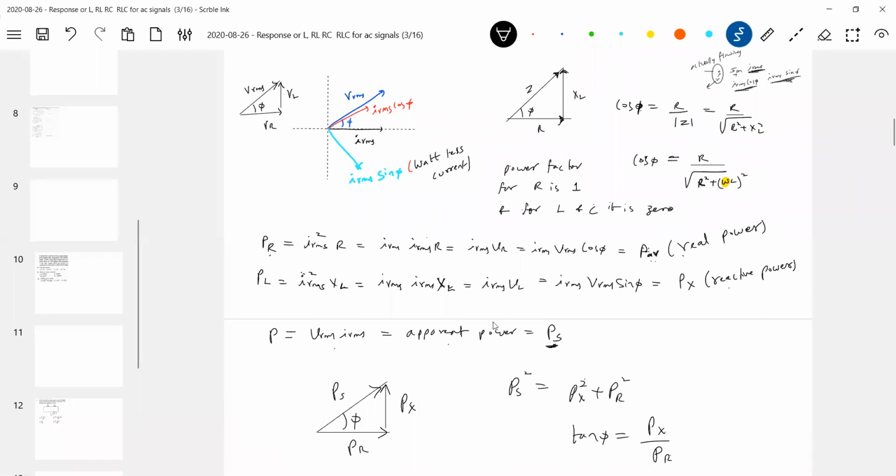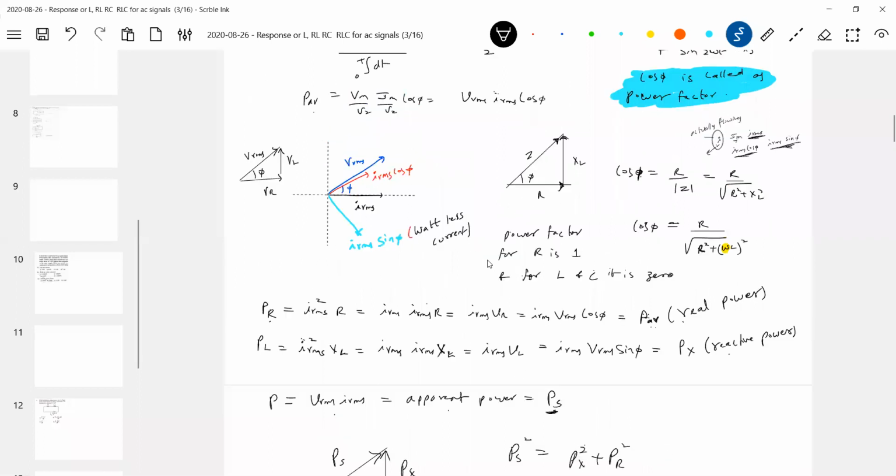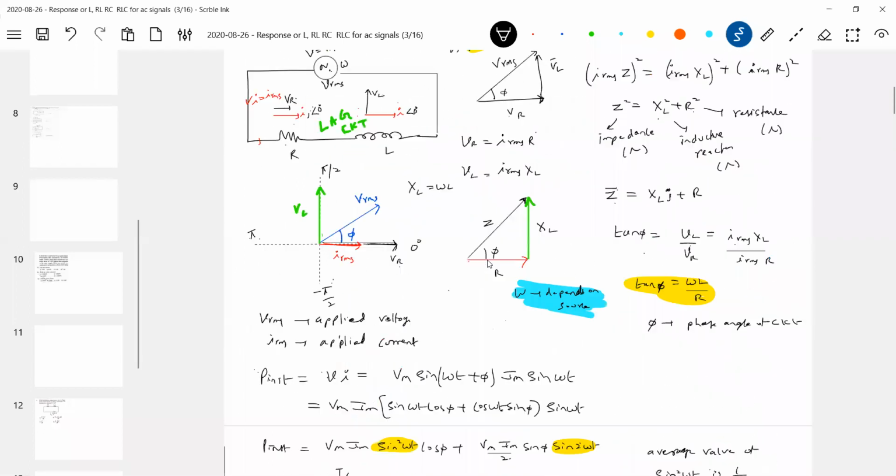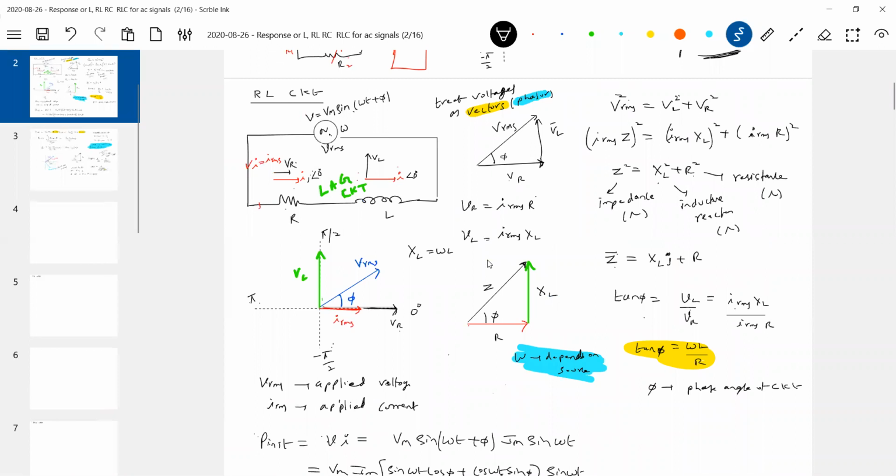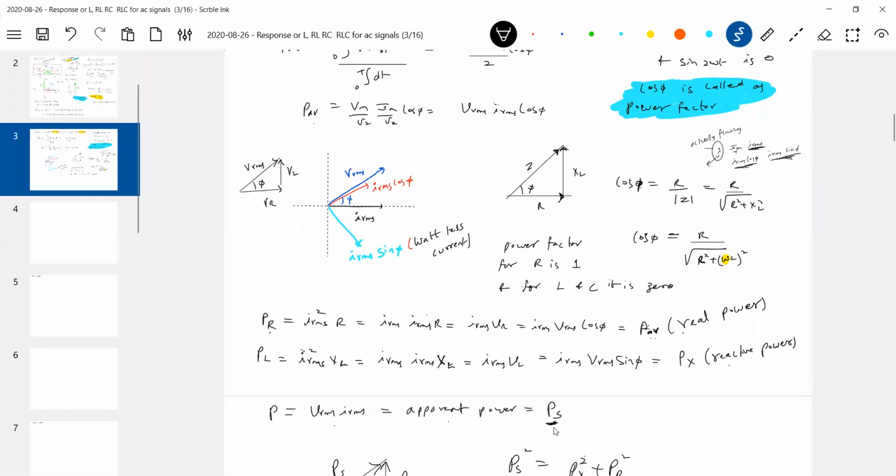Okay, this is about all the conclusion. So what is an RL circuit? An RL circuit is a lag circuit, which will make the current lag the applied voltage. And in this, who will consume power? It's actually only the resistor which will consume power. So reactive power is not dissipative power. It's only an exchange of power that occurs between the source and the inductor. And when the cell gives any power to the resistor, it will dissipate it.